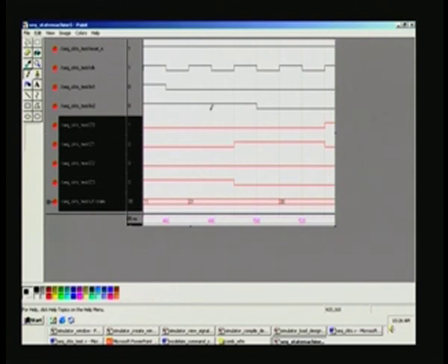In S1 state again it is continuing to be the same, and therefore, it remains in the same state, and once again at this point of time there is a change in the inputs. So, it is here 0 0. If it is 0 0, it should naturally take you to 0 0 state, and in this earlier thing it was 1 1 here. So, the Z3 output is set here, and it will change state for this state only at the following positive edge. That is why this is always delayed by a clock pulse, right.